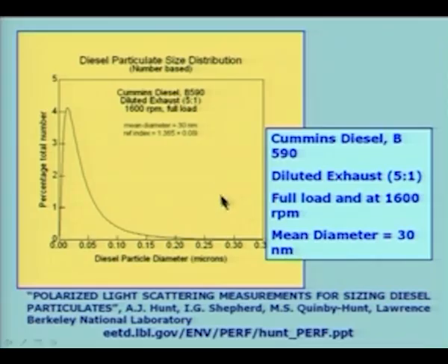That is why I said in the beginning that the difference between smoke and soot is only in the size distribution of the mean diameter. In this case the mean diameter is 30 nanometers, which will correspond to some value here. This is 0.05, so 0.03 is where you have to look. This is given in a scale of microns, so 0.03 is somewhere in this portion.